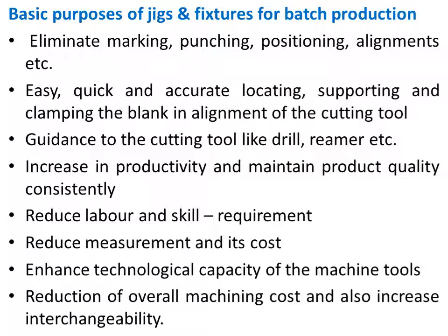Then easy, quick and accurate locating, supporting and clamping of the blank in alignment with the cutting tool. That is done by having the fixture properly located onto the part. Then guidance to the cutting tool like drill and reamer. That is why we have already made a pre-drilled hole onto the jig, which will act as a guide for the drill or reamer.